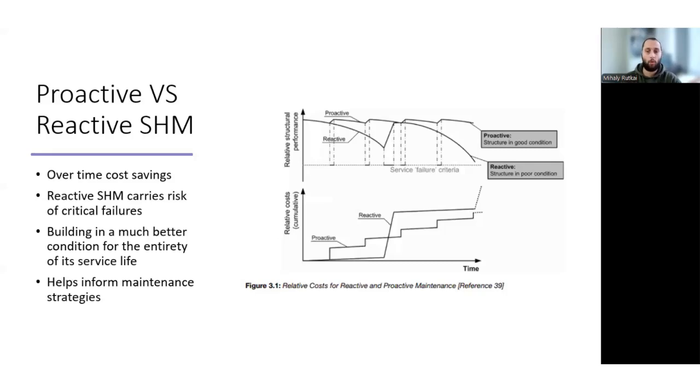For example, many old apartments, especially around Sydney and water, are showing signs of aging, from deteriorating facades to spalling balconies. In cases like these, drone imaging and infrared thermography can identify defects without ever needing to step through a residence. Ultrasonic pulse echo can identify voiding or cracking in a compromised concrete slab, while half-cell potential testing can identify areas of high corrosion chance before any visible defects even appear.